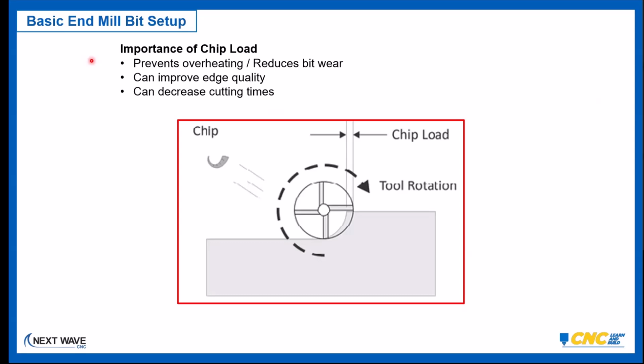And when you stop your router bit, the big guys who run the big machines say you should be able to touch the router bit after it stops rotating, and it will not be too hot to touch. Now, that's not always the case with the benchtop tools because we generally are running a little faster than normal on these, but I'm going to show you a couple of pictures later on that'll give you a clue of how good a chip load you really can get off of these tools.